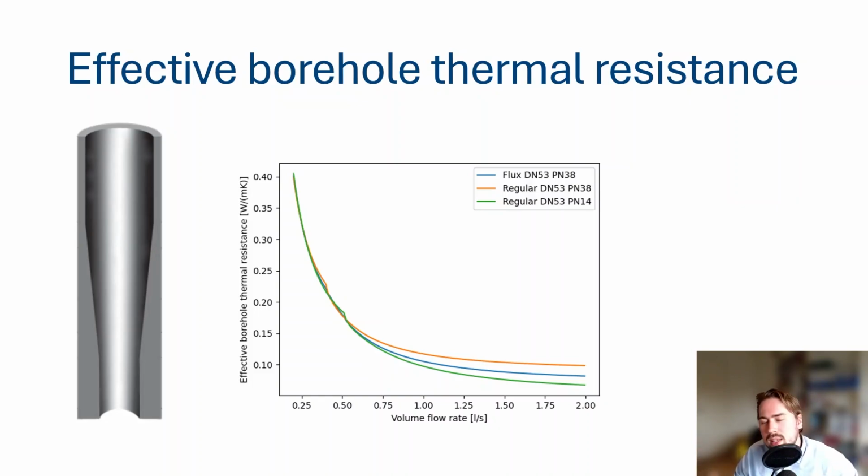So this effect kind of compensates, as you can see around this region. A regular probe transitions to turbulence, but our flux probe mostly is still laminar. But due to the fact that our laminar flow in combination with the lower wall thickness in the beginning also has an advantage, that's why in this region the difference is not even that big.